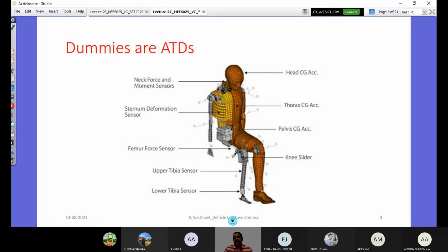So you see that the vehicle is completely digitized and discretized in terms of elements and nodes, with the placement of human dummies. There is a family of virtual mathematical dummies with these kinds of accelerometers, load cells and strain gauges all engaged with them, and then to find out the severity level, it all ultimately leads to testing the efficacy of the restraint system in your vehicle. So this is the advantage or highlights of ATDs.